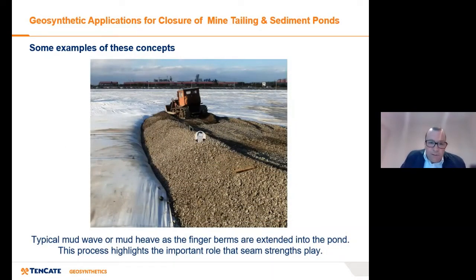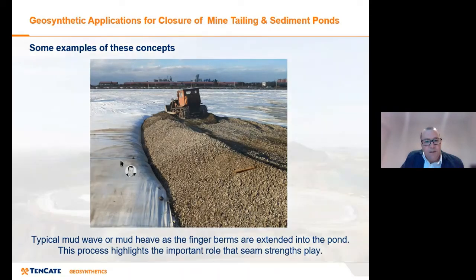And the point of this photo is to show that sometimes the mud wave can be quite significant, and if you're putting load on and the sludge beneath is moving that much, you've got to be able to ensure that your material stays together. So those seam strengths are important and need to be considered so that you're not having gaps open up within the reinforcement layer.